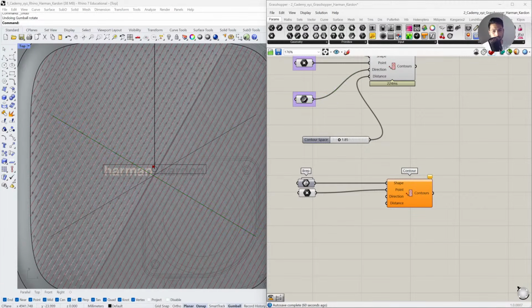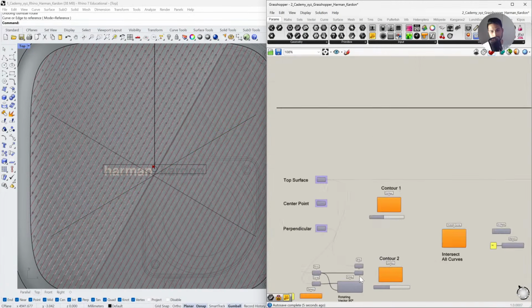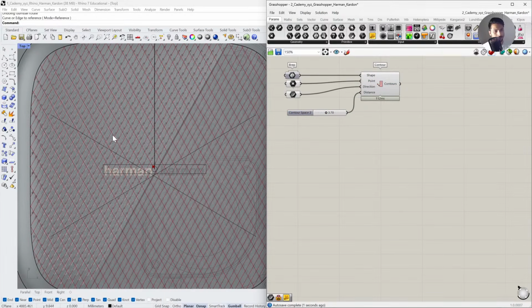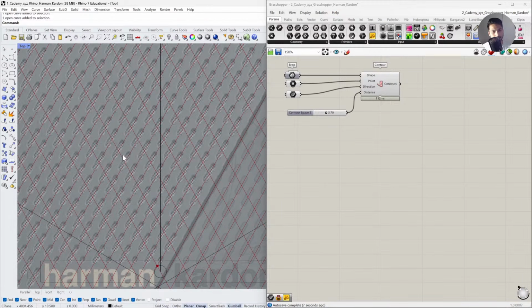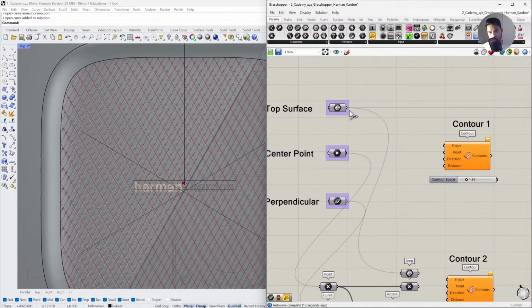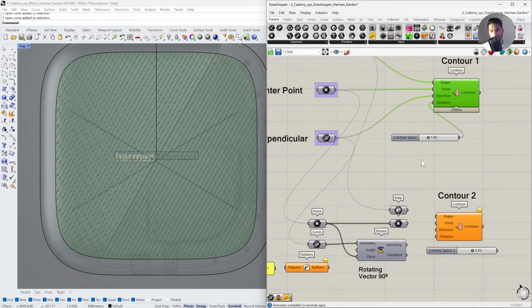Okay, so you can import that curve in Grasshopper as the distance, a direction, and for the distance, I think in this case is 3.7. Okay, and you can see here how we are able to redo the intersection between the two curves. Now for people who are following this part, let me redo it here. Shape, point, direction, distance. Okay, and for the bottom, shape, point.